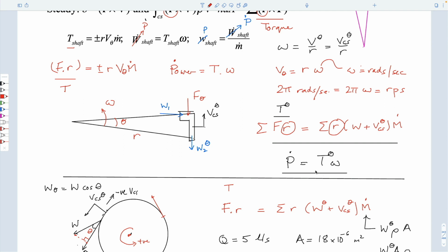And actually this would work out exactly the same as we did yesterday, Wednesday. When you're holding it and the torque is a maximum but there's no rotation, then the power is 0. When you're releasing it and it's rotating freely, so the speed is a maximum but the torque is 0, there's no power. And somewhere in between there, when this is finite and this is finite, you yield the maximum energy from the system, which is the same as driving a turbine. You have to have a load on it, and it has to be moving. If the load is on it but it's not moving, then it's not making any power.